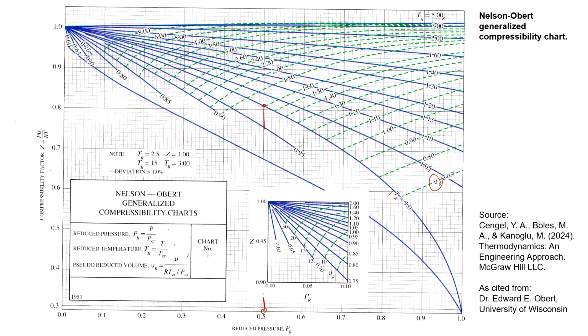From 0.5, you project a line up to the corresponding reduced temperature, and from that intersection, project a line to the left toward the compressibility factor axis. Then you obtain your compressibility factor, so Z is equal to, say, 0.8, or if it's somewhere in between, you just have to read the lines.